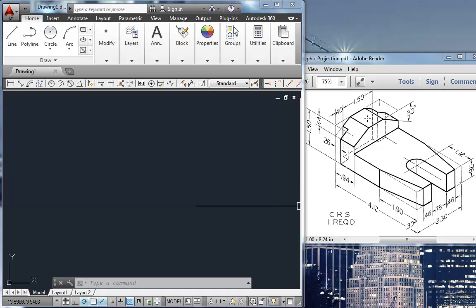Looking down on it will be the top view. And looking in from the end over here, looking in this direction at the part, this will be the right side view. So imagine unfolding this, if you will. So we could see the top, front, right side. So if we unhinge that kind of box, we'll lay those views out: top, front, and right side over here.